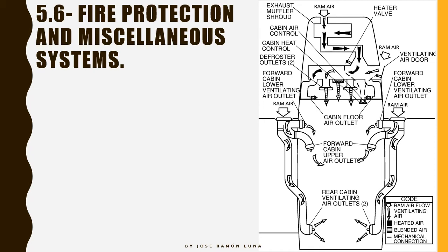It's not your choice. But anyway, the only one that is always going to be there is the ventilation one, the ram air coming from the outside straight to the inside. That is going to allow us to ventilate that cabin and that cockpit and basically keep us alive, right? So first things coming in right here, we're going to take a look at the diagram. These are the inlets for ram air. Okay, so we have the highest ram air right there in red.